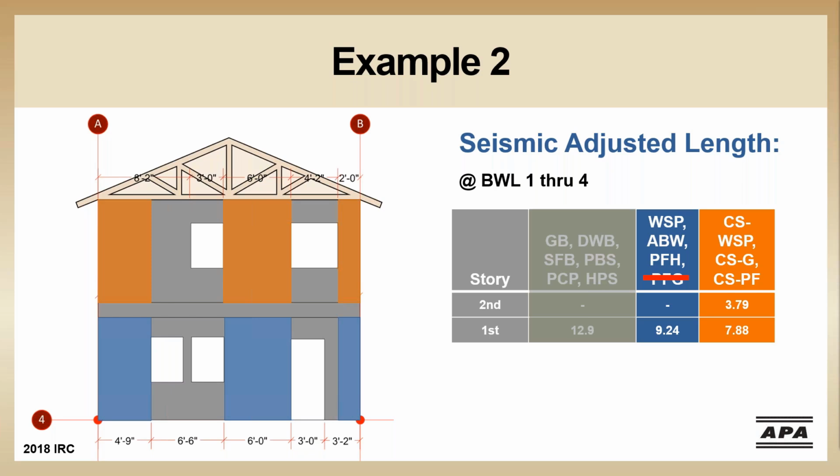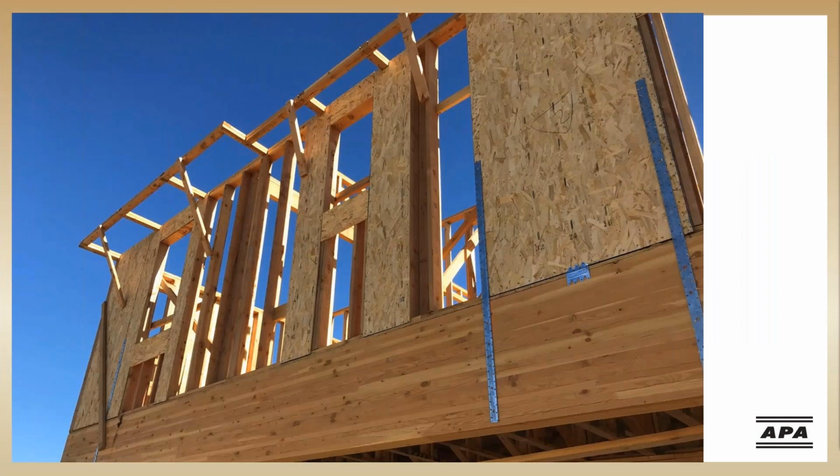In order to keep a braced wall panel within 10 feet of the end of the braced wall line, we are forced to have at least 2 panels. If you really wanted to get stingy, you could make both braced wall panels exactly 4 feet long. However, again, your framer is likely going to be adding most of that sheathing back in around the opening to attach the window flashing. So before you go through the extra effort of reducing everything to the bare minimums, just think about what you're really saving and what the installer is going to put in. Because I've definitely run across this type of situation a lot.